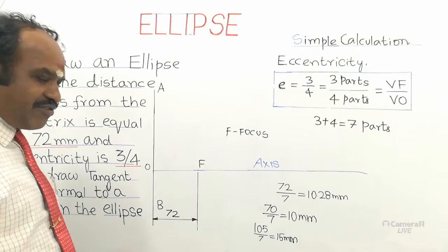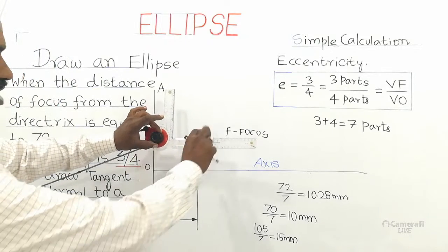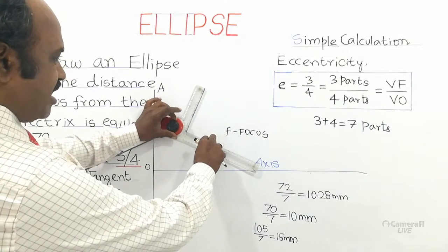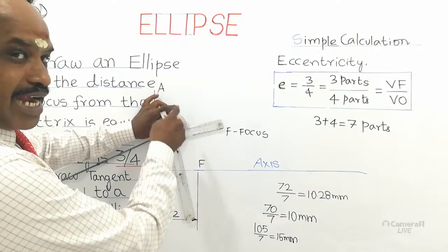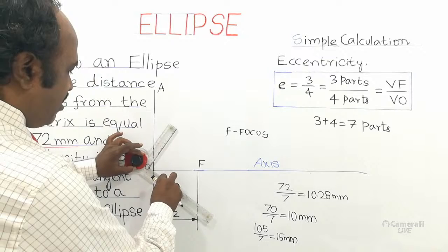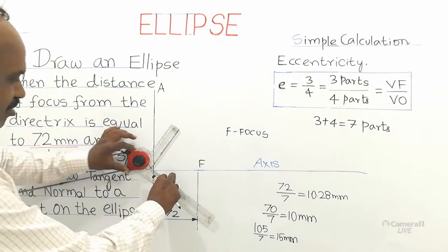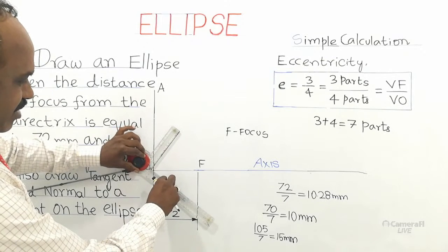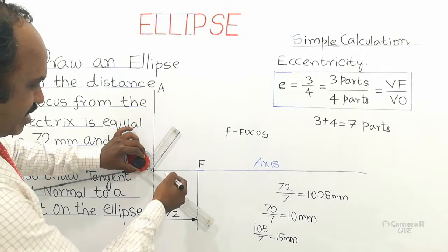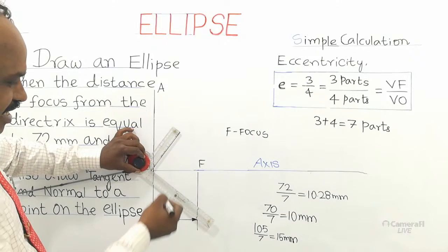So we follow a procedure for this. The drafter scale has a nut. Rotate that nut anticlockwise. The scale will be released like this. Rotating the nut in the anticlockwise direction, the scale gets released. Then draw one inclined line from point O. Then tighten your drafter scale by rotating the nut clockwise. Rotate clockwise and the nut gets tight, the scale gets fixed like this. Using this scale, draw a suitable length at any angle. Any length at any angle.